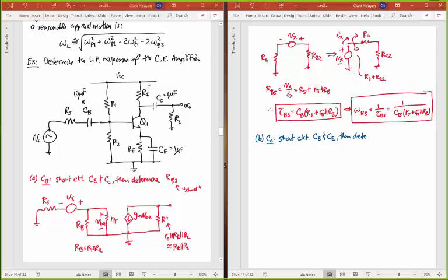Then with that, I want to determine the driving point resistance associated with capacitor C sub C, and I have to zero out my source, which is V sub S. Okay, so if I do that, looking at the circuit up here, and plugging in my small signal circuit, zeroing out V sub S right there, I have Rs coming in there. I have that string of bias resistors right here, RB. I again have R pi with voltage VBE across it.